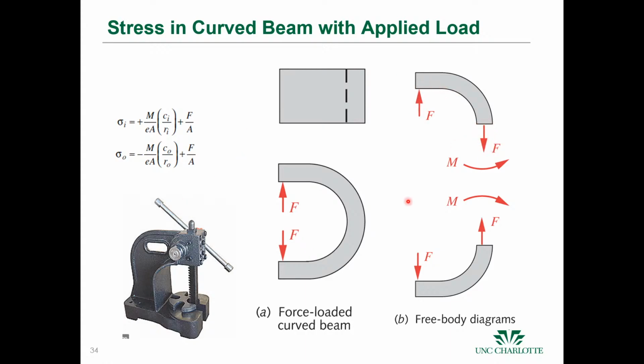If we cut this cross-section right here, the balance of forces is that this force has to be equal to this force, but we also have an applied moment to prevent this from moving. So then we can still calculate those same equations with the same geometrical relationships. We just have to add this force due to the applied load on this cross section so that we can find the stress.